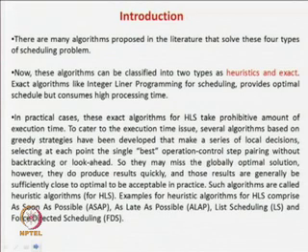Now, before going to these algorithms, in VLSI, as we will prove in the end, the scheduling procedure is a hard problem. It requires exponential time complexity. If there are n operations or n time steps, to find the best possible schedule the complexity will be in the order of 2 to the power n. Assume your specification has hundreds of variables and you require hundreds of steps to do a practical schedule. Your complexity will be 2 to the power 100 plus, which is very infeasible.